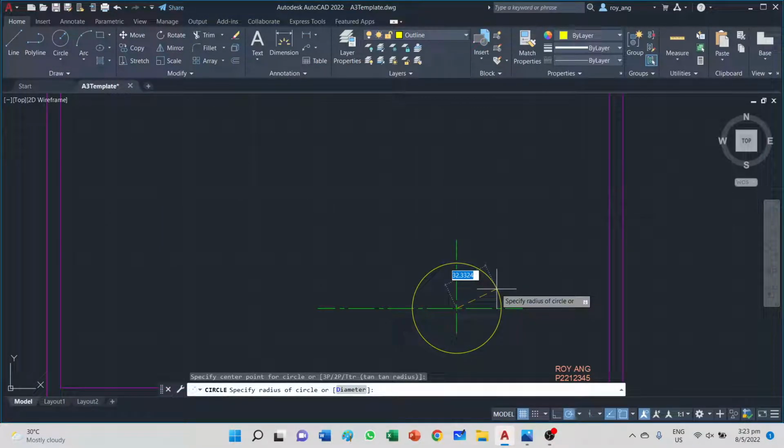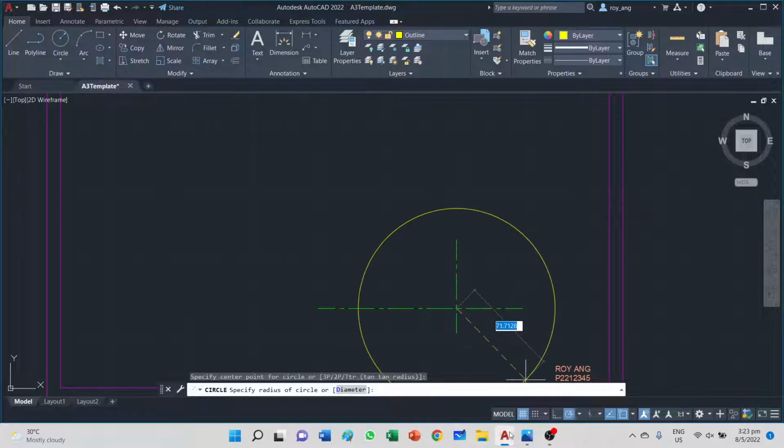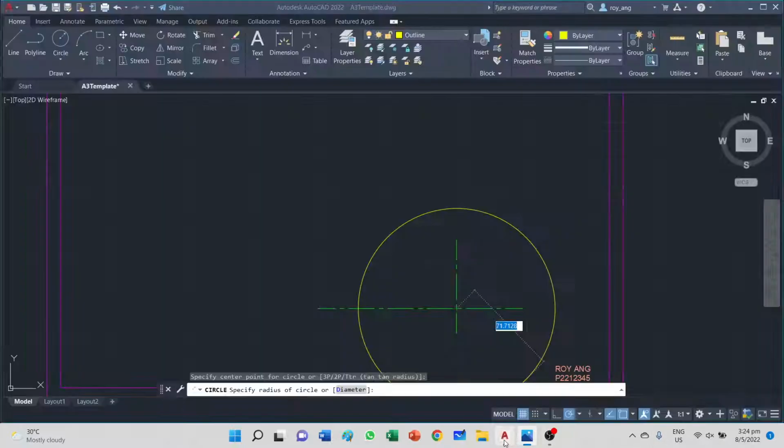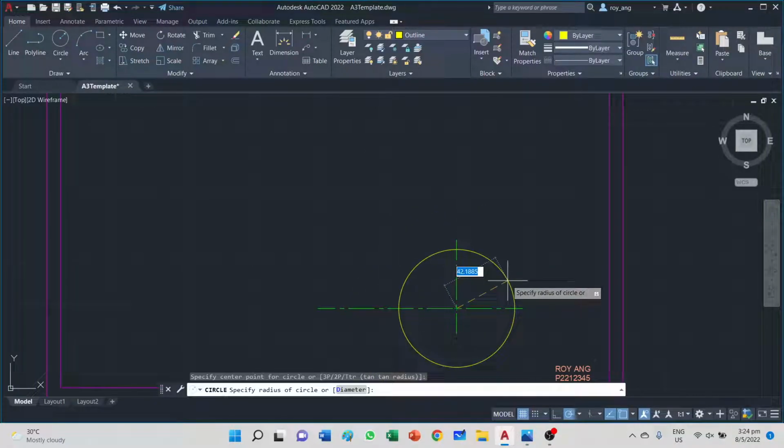So the first arc that I see is, let's toggle back here, I'm going to draw this arc. There's a full circle and then I'll trim it into a half circle, R24 and R38, and then I'll draw the base and then I'll work up through the web and the top over here. I'll realize that I'll come into some obstacles with dimensions that are not known, and I will stop halfway. You have to feel comfortable with stopping halfway. So this is R24.